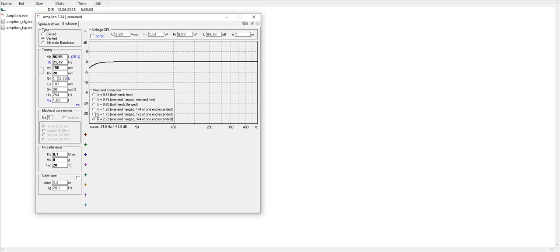LV is the length of the vent. The length of the vent determines its first self-resonance. It is a common phenomenon and can be measured with a microphone in the near field. Standing waves also pass through the vent, so it is not easy to determine the resonance precisely. VA and MA are the parameters of minor importance.